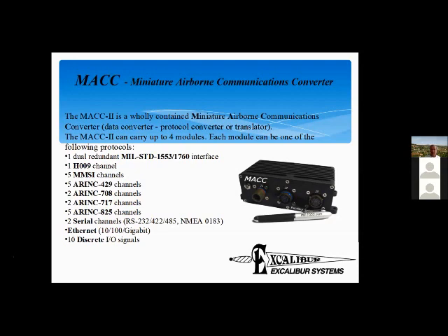Now it turns out not to be easy to replace it because the box of the inertial navigation system was fit exactly into a particular place on the helicopter. Which means that your new box better fit into the same place. So it has to be the same fit. You'd prefer that it not be heavier. You'd prefer that it not take more power. You'd prefer that it not be hotter. So you've got a lot of preferences here, some of which you can flex on, some of which you can't. And let's say you found, and of course, you want functionality.